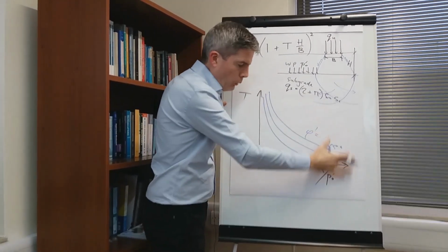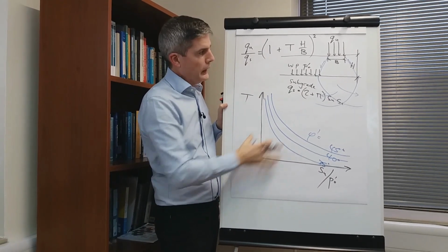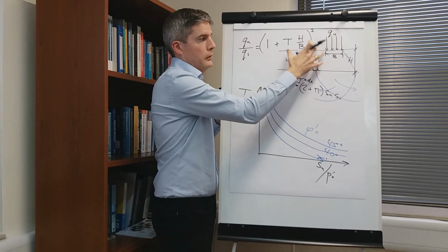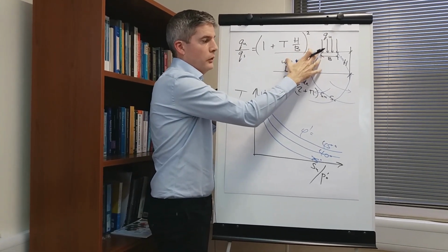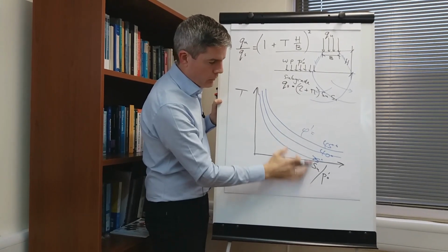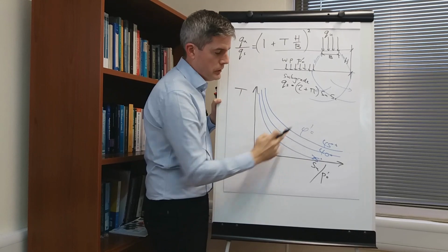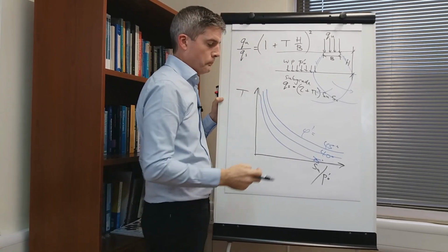So in one chart, you can see how the bearing capacity of a granular layer in a working platform over a subgrade depends on the relationship between the shear strength of the subgrade and the shear strength of the granular layer.